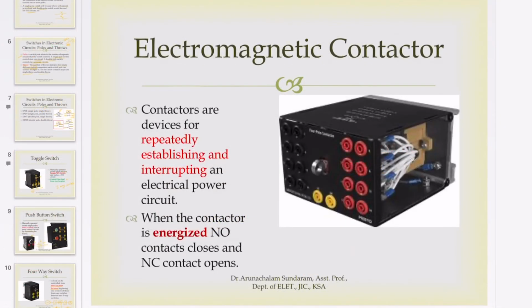Now for the electromagnetic contactor. Contactors are devices for repeatedly establishing and interrupting electrical power circuits. When the contactor is energized, normally open contacts close and normally closed contacts open. That means, guys, this is the electromagnetic contactor.